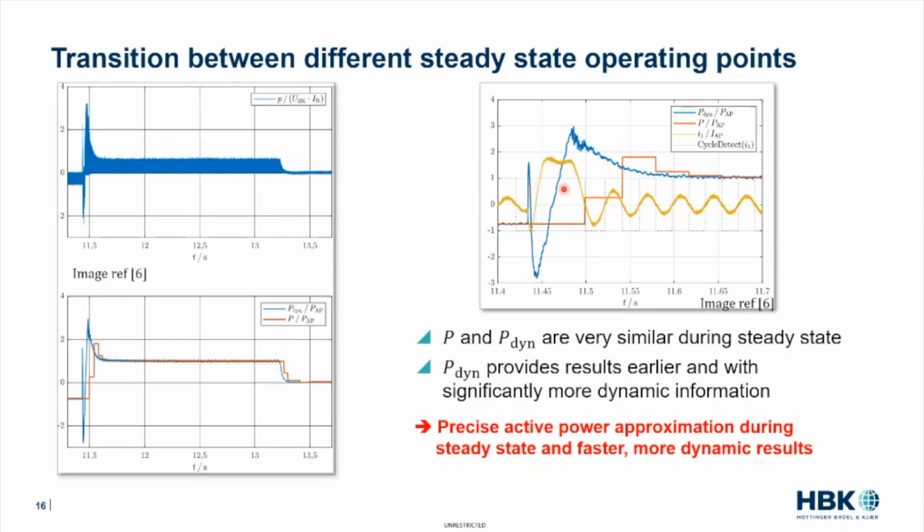You see the same here, which is, I think, just a zoomed version of that. So when you do a cycle-based power calculation, which so far with our system is the fastest you can get in the market, you still don't get the full amplitude of the power which is drawn by your drive to accelerate or to change torque in that case.